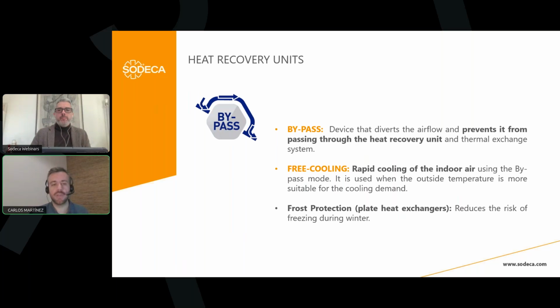On the other hand, it is also important in plate heat exchangers like the ones we are presenting today, that we could have a frost protection. Okay, reduce the risk of freezing during the winter. If we have low temperatures outside and we don't have an electrical preheater, which is very common in some climates, the bypass will allow us to protect the exchanger. Okay.